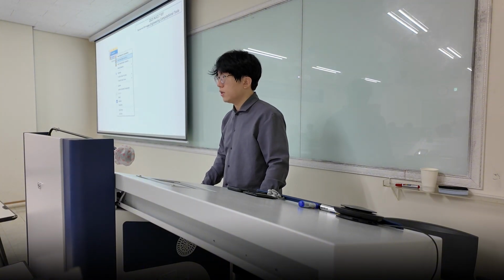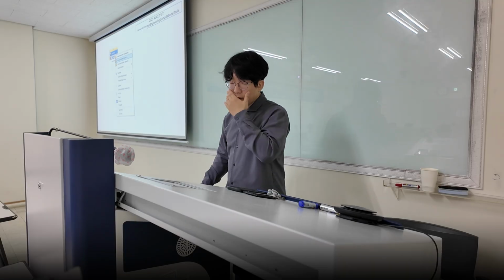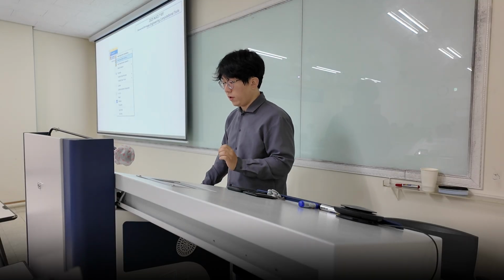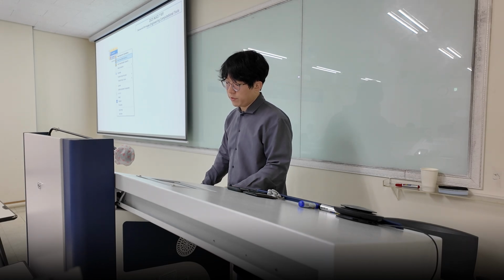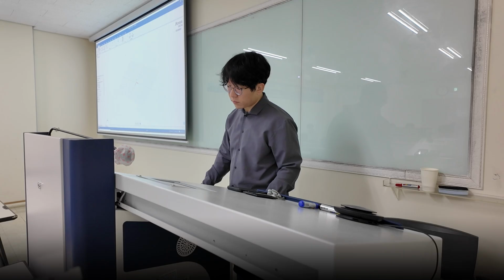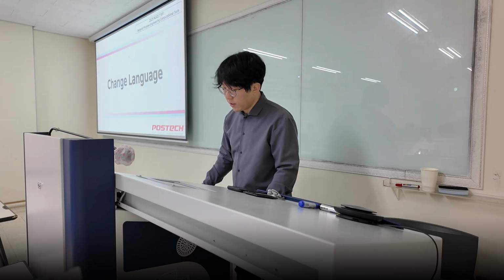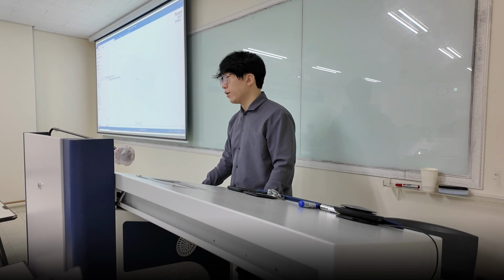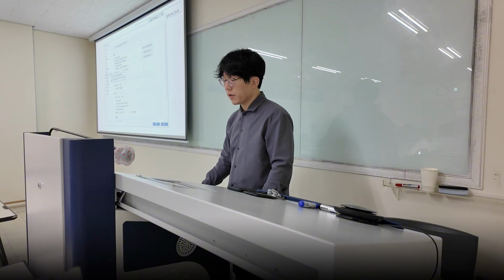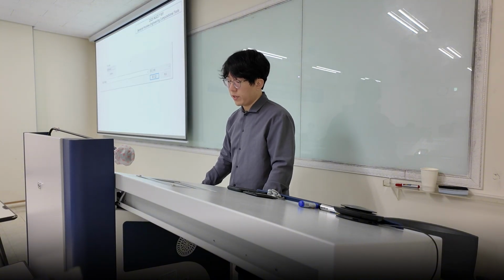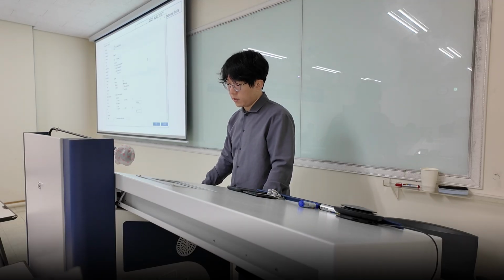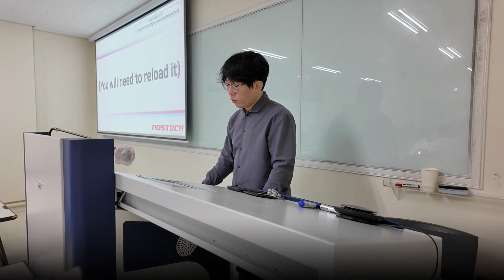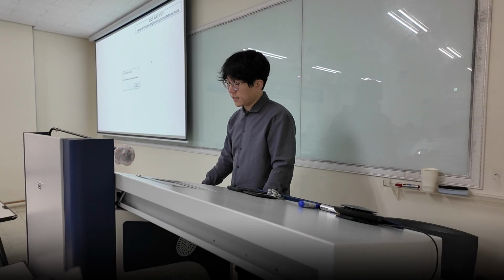There's a platform to load the STL files. You can either use Discovery Geometry or SpaceClaim Geometry. We're gonna use SpaceClaim Geometry. It's really important to choose a language because later on you're gonna encounter an error. What I'm showing you here is, of course, you're gonna load an STL file, and later you're gonna encounter this error.